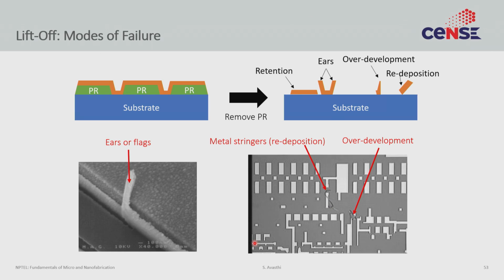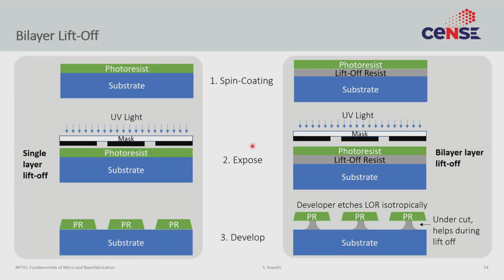So one way you can enhance the success of your lift-off is to try a lift-off resist. So what is a lift-off resist? So you just look at the figure. So a simple resist is you have a substrate, you have a photoresist, you shine UV light, you pattern the photoresist, done.